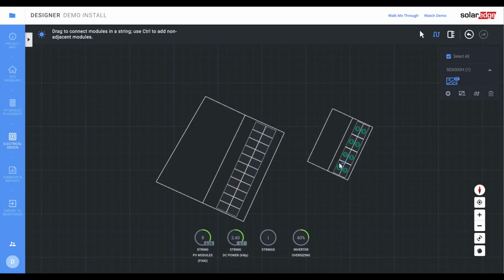And so in this scenario, 8 creates the minimum viable amount of power in the string. And I think from my calculations, with the 300 watt panels, it's around 18-ish panels maximum that you can have in a string, I believe.